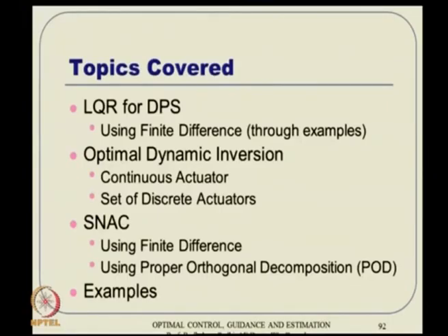So, there is scope for bringing in calculus of variations a little bit, and then we solved for controls assuming a continuous actuator, and subsequently we had the discrete actuator formulation, where control singularity starts coming as the objective starts getting met. So, there was a necessity of switching over, with two goals, one in the beginning and one towards the end. We demonstrated that utilizing examples also.